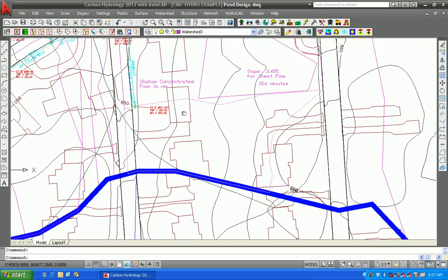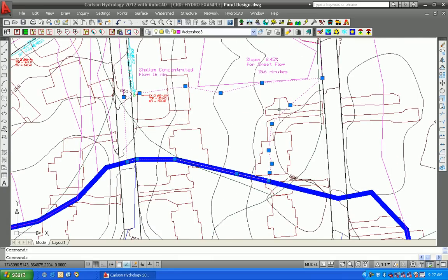So here we've drawn a perimeter that uses some human judgment, where this building, the front of it would drain to the street, the back of it would drain out in the westward direction and feed into this inlet.